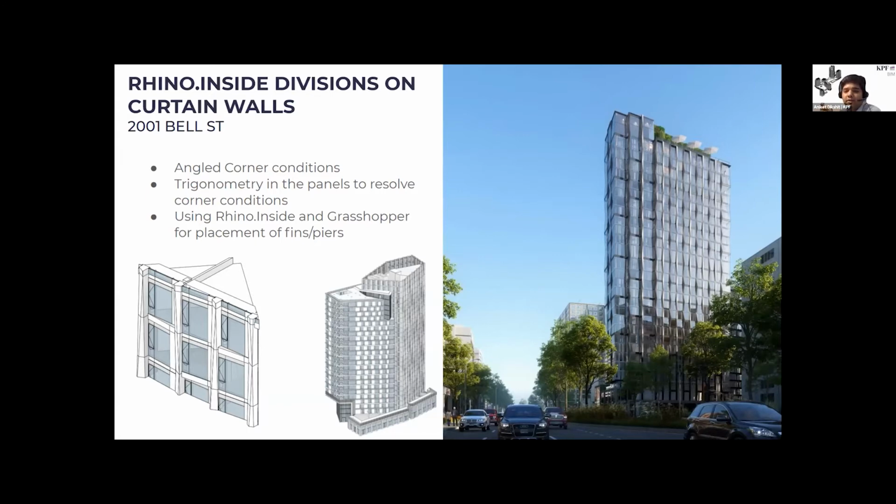And that reduced the load on the team, so that they didn't have to design in Rhino, export an Excel from Grasshopper, absorb that Excel in Dynamo and replace that inside of Revit. And as we all know, Dynamo's geometric calculations aren't the best. So we were able to utilize Grasshopper for what it does best, which is geometric based calculations.